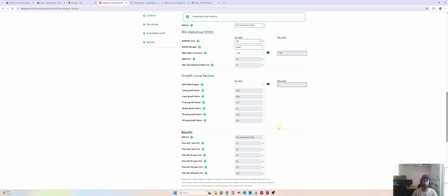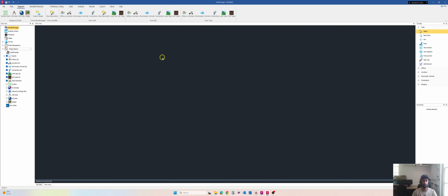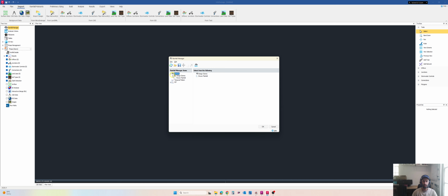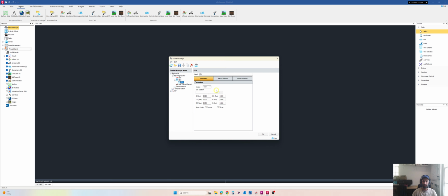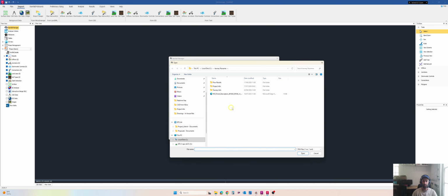Now what we can do is open our InfoDrainage. Once we open InfoDrainage, at the top we have this field, the rainfall manager. So we will set up the rainfall manager and the design storms for FEH, and we will load the FEH file.